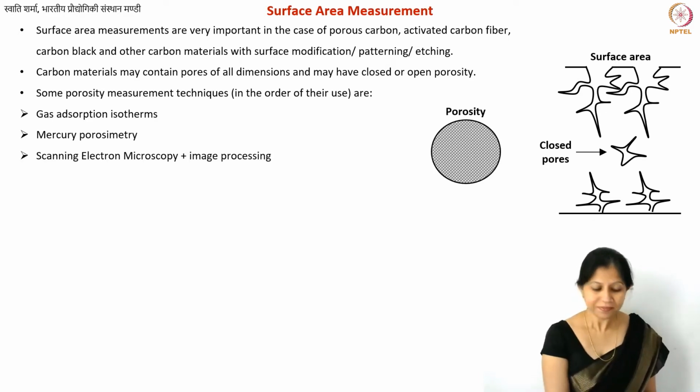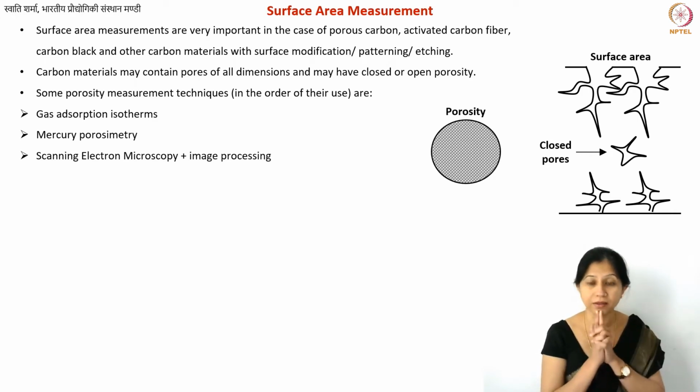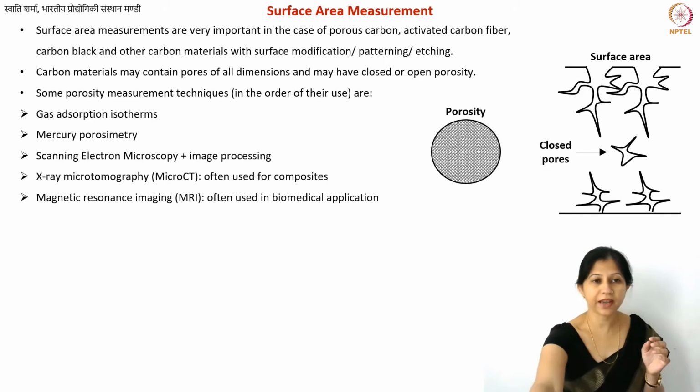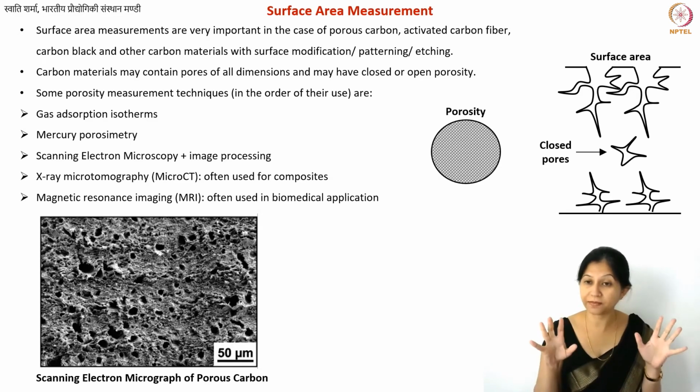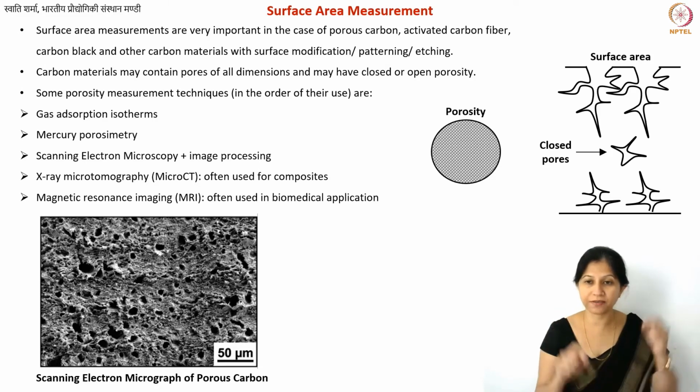This is yet another technique: SEM imaging. So we talked about TEM. SEM, how can we use that? Let's see if I have a picture. Yes, I have it here. So an SEM image of porous carbon, you can see, will only tell you about the surface, right? You should know that you will only know about the surface and not whether your pores are cylindrical, how deep down they go, and also whether or not your pores in the middle of the material are connected to the top layer. So you'll only get the top view if you take this kind of standard SEM image.